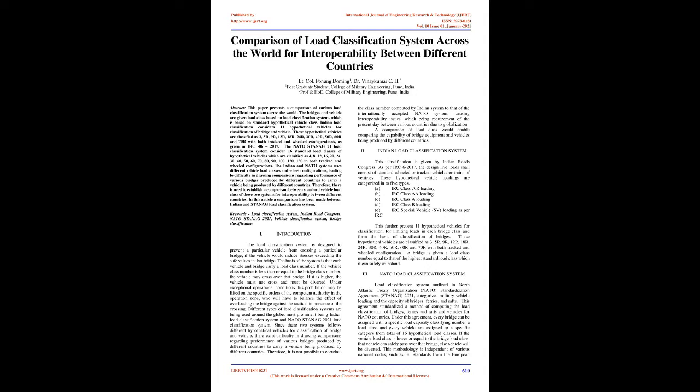IRC-06-2017. The NATO STANAG 21 load classification system considers 16 standard load classes of hypothetical vehicles, which are classified as 4, 8, 12, 16, 20, 24, 30, 40, 50, 60, 70, 80, 90, 100, 120, 150 in both tracked and wheeled configurations. The Indian and NATO systems use different vehicle load classes and wheel configurations, leading to difficulty in drawing comparisons regarding the performance of various bridges produced by different countries to carry vehicles produced by different countries.